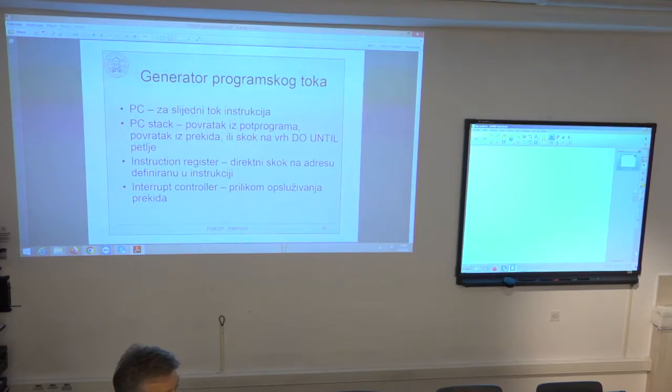in this type of application, usually the useful things are done in only a few assembly instructions. For example, computation of FIR filter 1 step, or maybe computation of this so-called butterfly in fast Fourier transform implementation. It takes 2 values, multiplied by some coefficient, gets another 2 values as a result. So all of these operations are done in only a few assembly instructions.